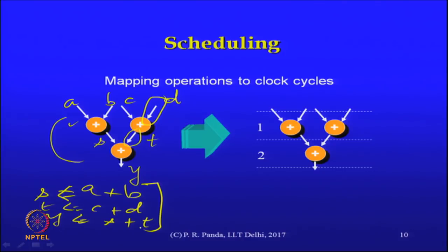These were 0 delay assignments that we specified, but of course, finally these things have to be mapped into clock cycles. All the operations do not necessarily fit into the same clock cycle. Whether a new clock cycle is necessary or not, how many clock cycles are necessary, this could be part of the scheduling tool's decision making process. It is an important part of the high level synthesis tasks.